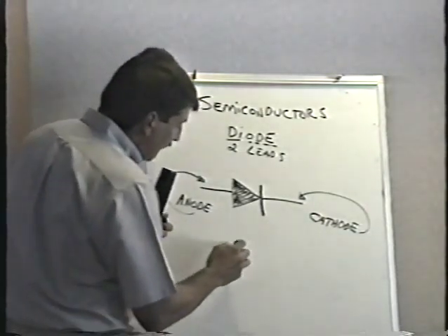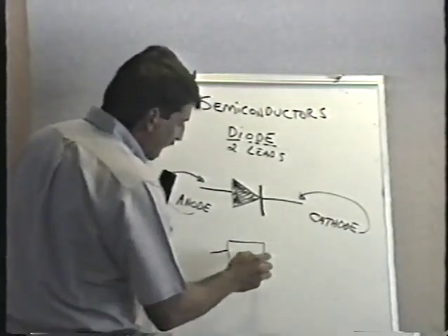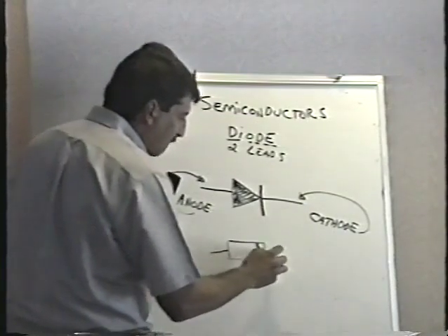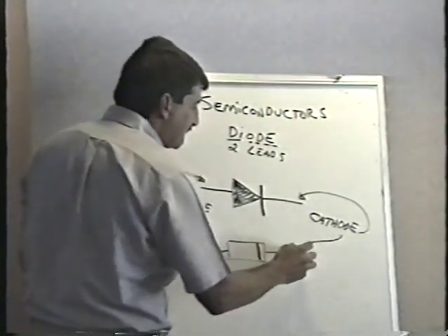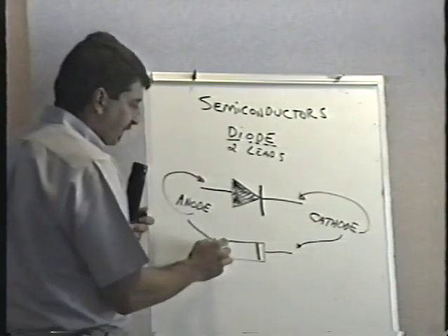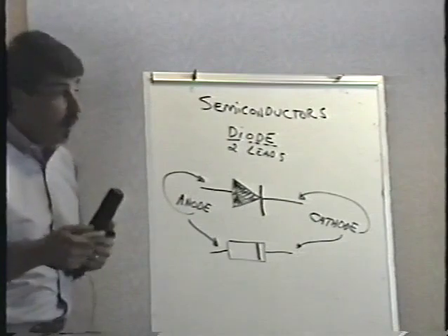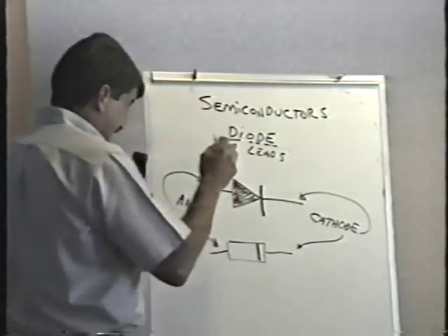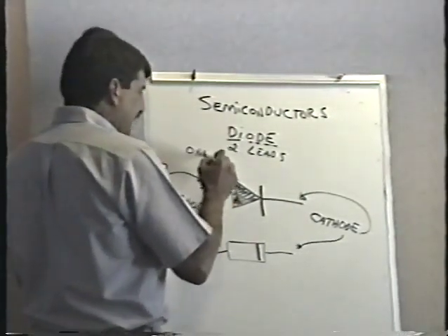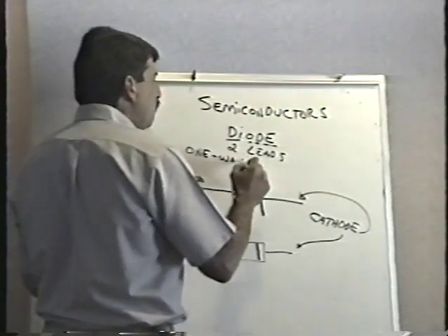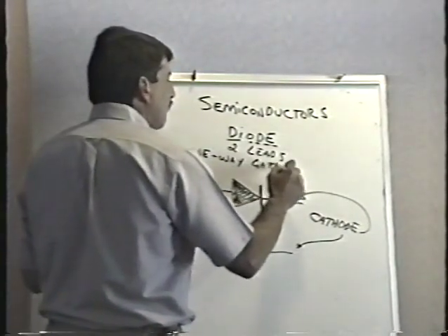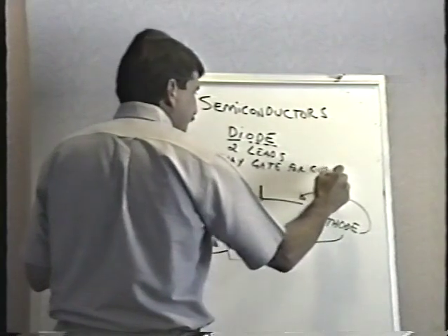And if you look at the diodes that I gave you, you'll see a ring or a stripe on one end. Obviously, that's the cathode end. And the other end's the anode. The reason that it's important to know which lead is which is that the diode is a one-way gate for electric current.